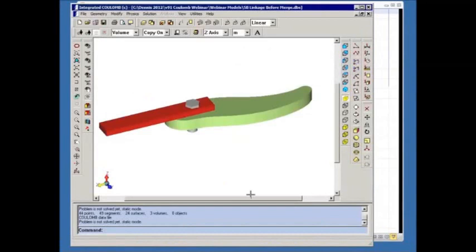Okay, so here you have a square or a rectangular block connected through a pin to another curved kind of lever or block. And these are all separate volumes. If you're doing electrostatic analysis, these would all be at the same potential. So it's handy to merge them into one single volume. So we'll do that now.